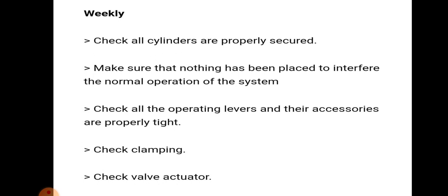Weekly means check all cylinders are properly secured. Make sure that nothing has been placed to interfere with the normal operation of the system. Check all operating levers and their accessories are properly tight. Check the clamping, check the valve actuator.